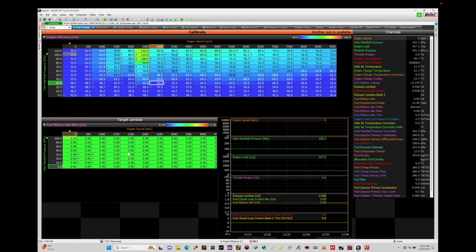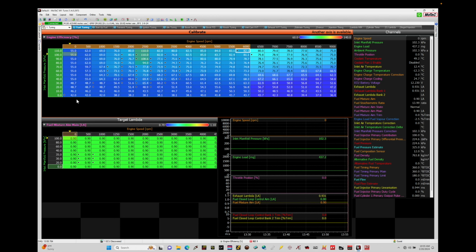That means that our air and fuel model has been sorted out 100%. We also have our charge cooling gain that we have to make sure has been calibrated. We talked about how to do that in previous training modules in our training course. That has been taken care of at this point already. So I've dialed my volumetric efficiency table in here the best I can from 6,000 RPM and below. I've set up the charge cooling gain as well.